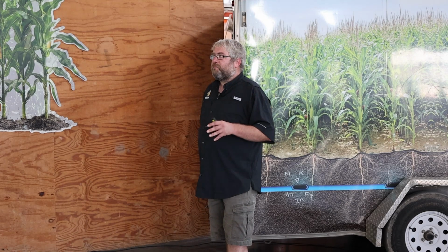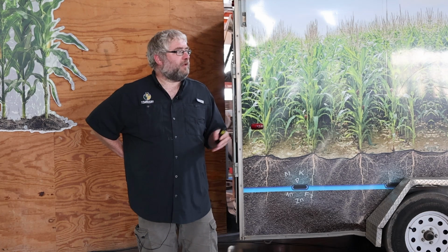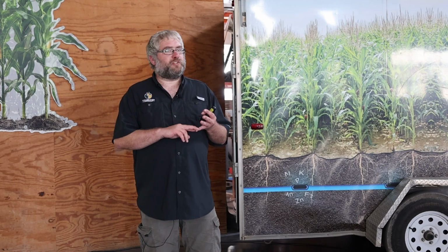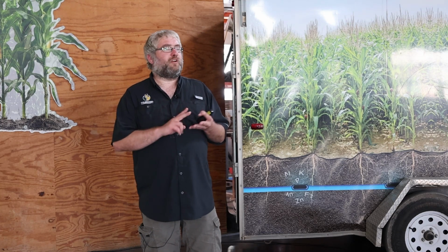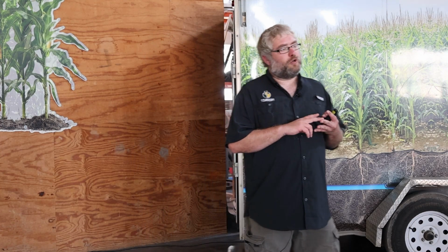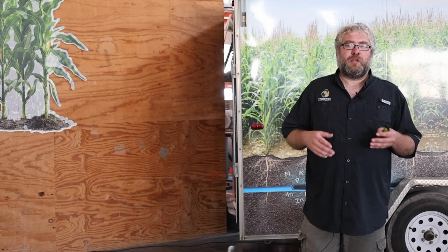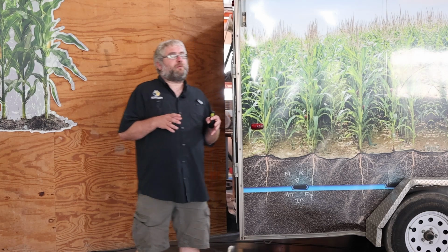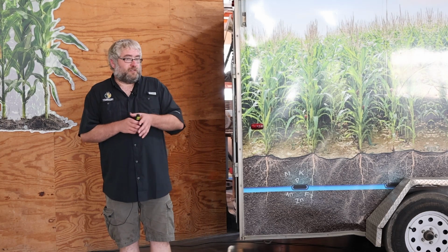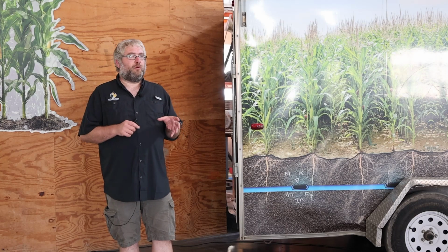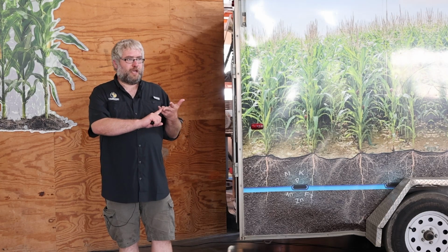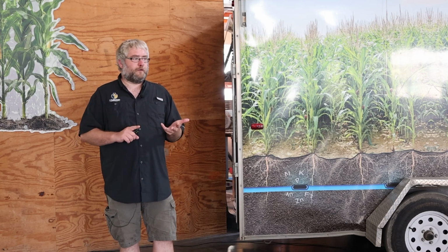We have built a really good data set between NutraDrip and Calibrated Agronomy on how the water we use in irrigation affects the mineral balance and available nutrition in the soil, and how to interpret that, and then the SAP test. Our approach, like Tim touched on a little bit, is with the rapid soil test, which gives us a look at what is available in the soil water solution when it rains, when we irrigate, or if we treat our irrigation water.